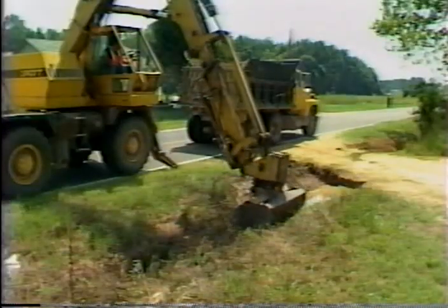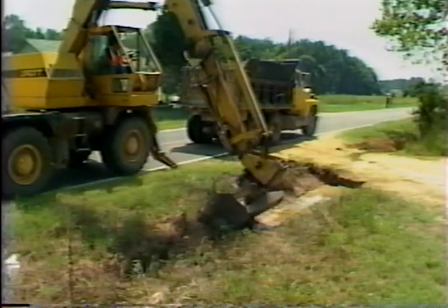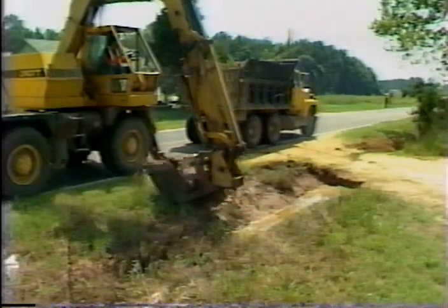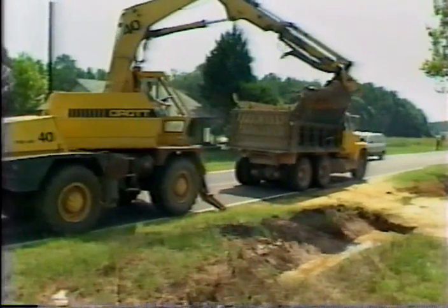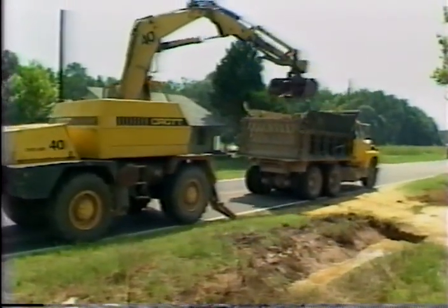This ditch does not have a proper flow line. Water is a principal cause of many structural pavement failures. Providing proper drainage through ditch maintenance is preventive maintenance and will allow pavements to last much longer.